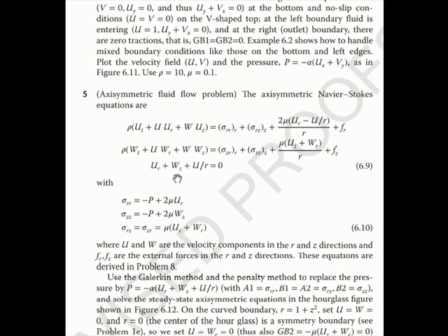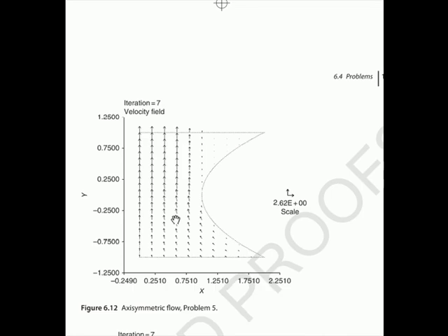You'd think it'd just be u_r plus w_z equals 0, but it's got this extra term and you've got these extra terms. And anyway, it's there and it's derived in another problem, but there's actually a problem where you solve the axisymmetric equations. And remember, the whole reason for using the axisymmetric equations is that it's 2-dimensional and therefore much simpler. In fact, you can use the Galerkin method again. So here's a problem where you're supposed to use the axisymmetric equations, and here's the region.